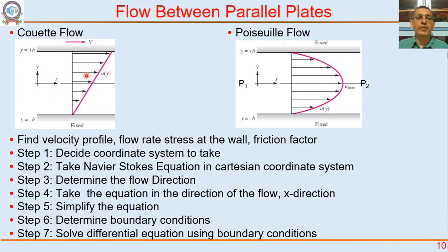The molten polymer is here, the plate is moved, polymer gets pulled, so polymer gets coated along with the plate, and once it is coming out of the gap between the two plates, it is immediately quenched, so the polymer solidifies. So I have a layer of polymer solidified on a plate. That's how I coat materials. All the polymer coated bags that you get are coated in this way.